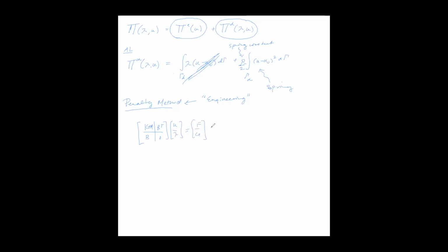And now we've gone to what? What's left? Well, just the K plus M. So now we're left with a method that is written just in terms of our displacement degrees of freedom. So we've reduced the size of our problem, and we've added basically this type of mass matrix to K.